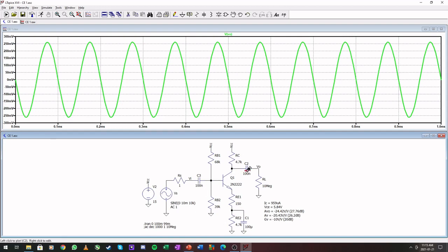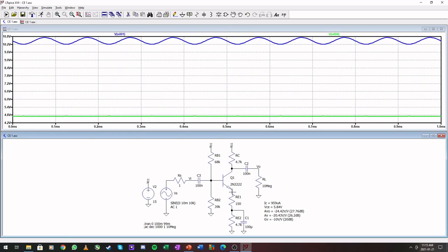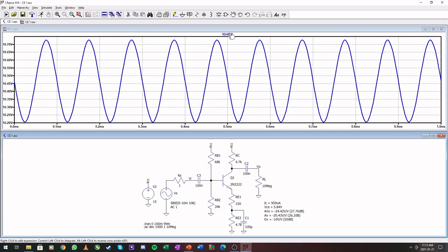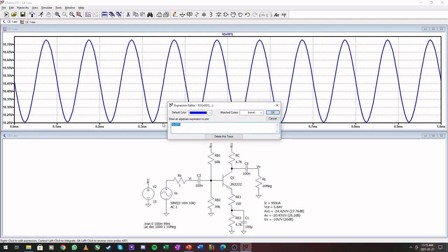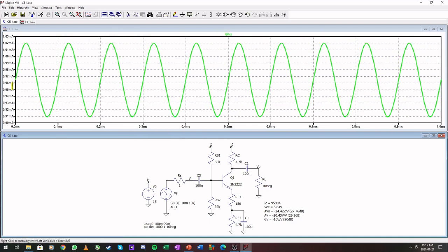In any case, we have a decreased gain. Our VCE value here, that is still node 4. 5.75, close to our 5.84, and 959 microamps. This is also close. If this was 1 milliampere, it would still be fine. So this design checks out.